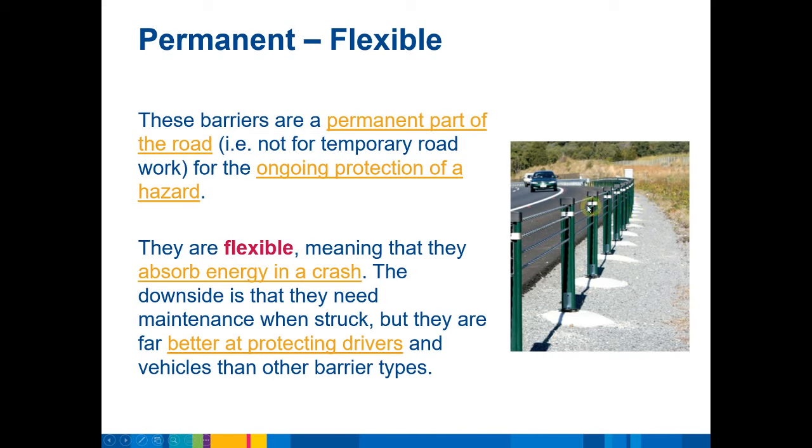They're way too big. A motorcyclist will tend to either hit the barrier and fall off over the top, because the motorcycle and the motorcycle operator are two separable units, or if they've fallen off before they hit the barrier, they slide into the poles and hit them at the base. So in either case, these are not particularly great for motorcyclists, but they are not the cheese grater that gets talked about. There's never been a single case of anyone being cut by these things. They tend to just slide into the bases and be injured, the same way they would be sliding into the base and hitting a pole, or sliding into the base and hitting a tree.